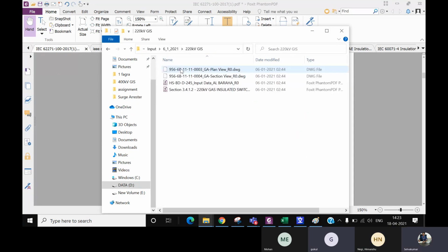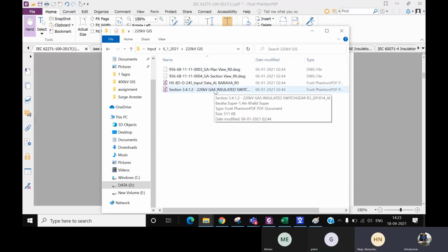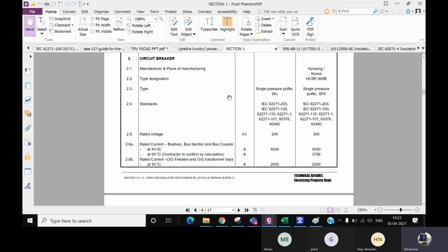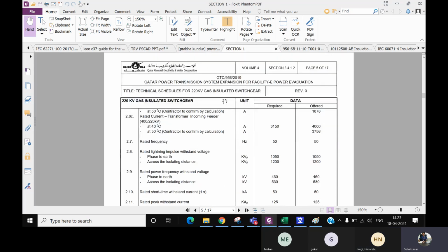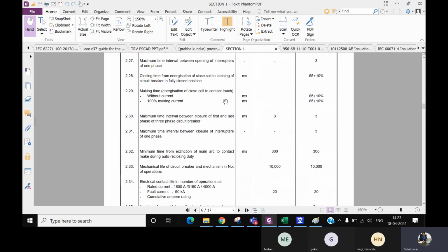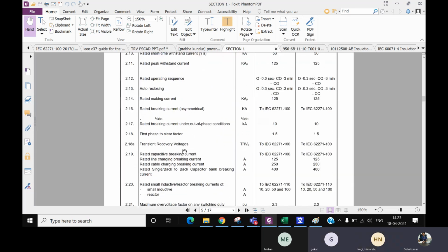But before that, this FPC 1.3, 1.5, you are clear, right, Himanshu? Yes, FPC 1.3 and 1.5. It is called your earth fault factor. Yes, exactly. For a solidly earthed system, we go with 1.3, and for non-effectively grounded systems, we go with 1.5. You might be using this quite frequently in your earthing, correct? I don't use that a lot, but I have seen it in some protection study reports done by some other guy for us. Yes, it is called earth fault factor.